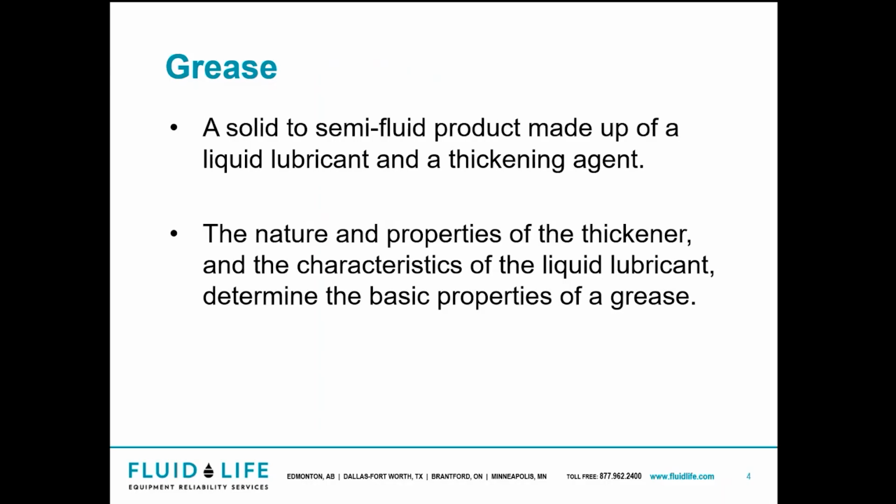So what exactly is grease? Well, grease is made up of 3 components. We've got our base oil, our additives, and our thickener. And all it is, is a solid to semi-fluid product made up of a liquid lubricant and a thickening agent. Now, the nature and the properties of grease come from the thickener, but the liquid lubricant within the grease is the part that still does the lubricating.